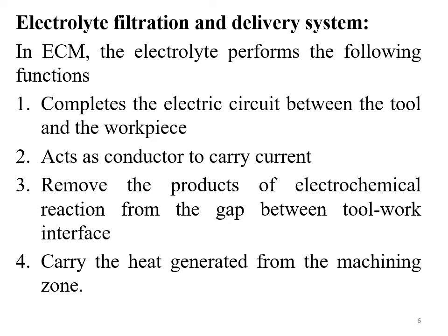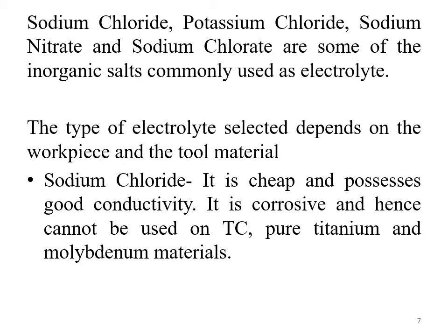That's why the heat generation needs to be completely eliminated, or the generated heat energy needs to be taken away from this machining zone. That major function is being carried out by the electrolyte, since the electrolyte is a solution, generally a salt solution, which takes away the generated heat energy from the machining zone.